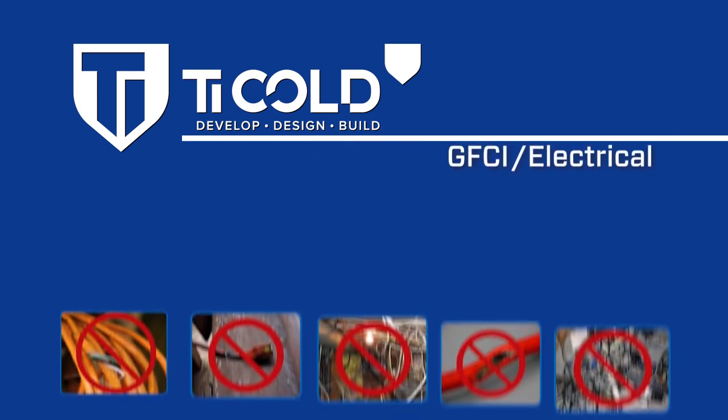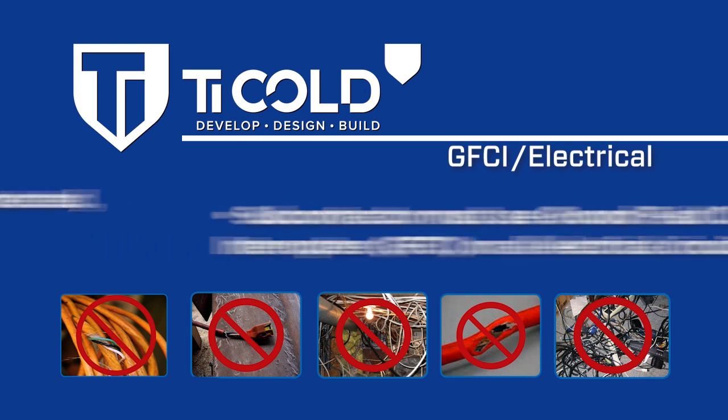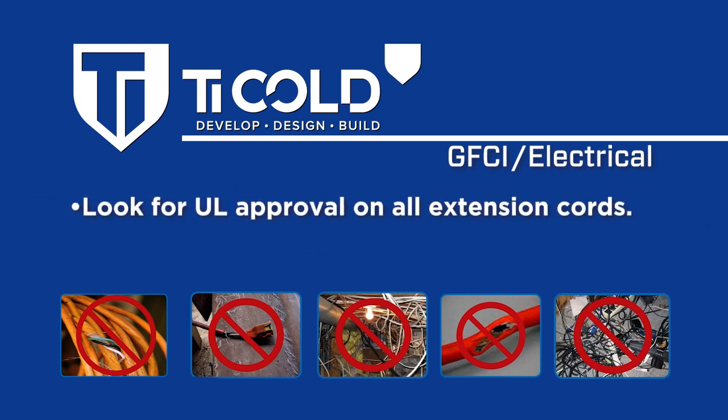GFCI electrical. Subcontractor must use ground fault circuit interrupters, GFCI, on all electrical circuits. All extension cords must be GFCI protected, grounded, and rated for hard surface, sufficient amp capacity. Look for UL approval on all extension cords.